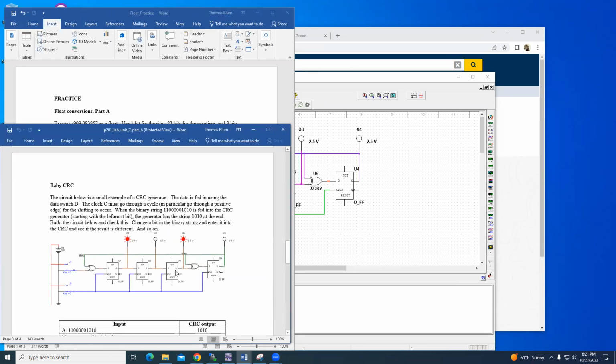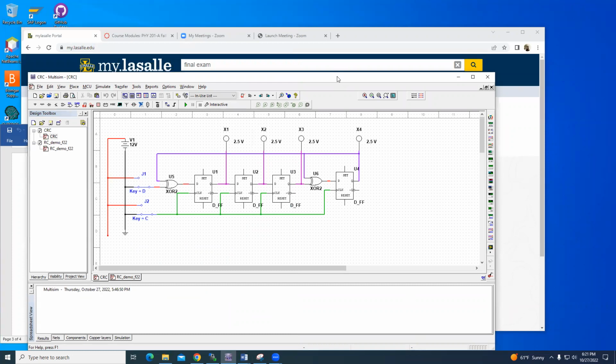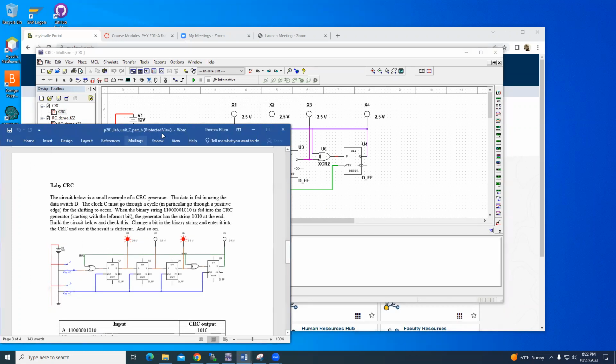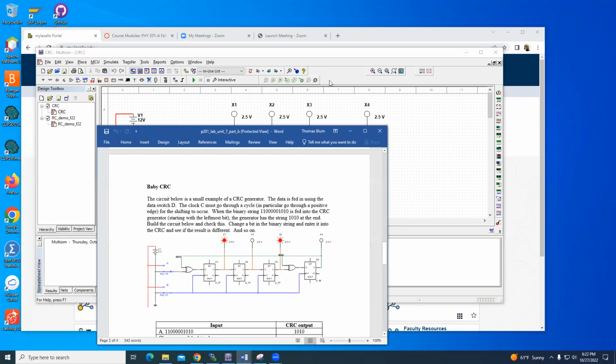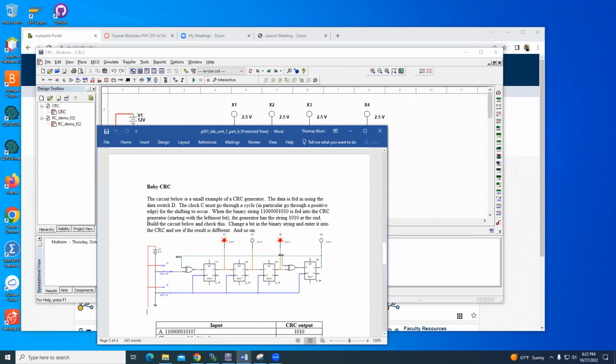So you get these latches or flip-flops. They have a data input and a clock. If it's called clock, that means it's edge triggered. That means you have to go through one of the edges of the clock in order for something to happen. Let's see if I can give you at least the first one here. I'm going to read in this data, 11. I'll try to read it, even though it's got a bunch of zeros.